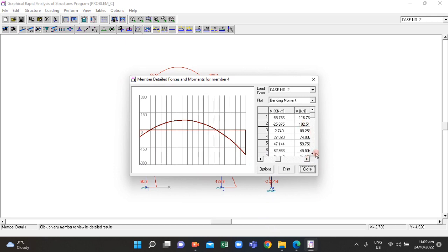The maximum moment is where the positive and the negative shear meet, at 0. So I'm just going to evaluate it using judgment. Here we can see 2.750 to negative 11.502.